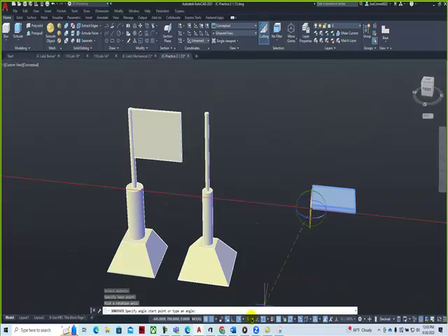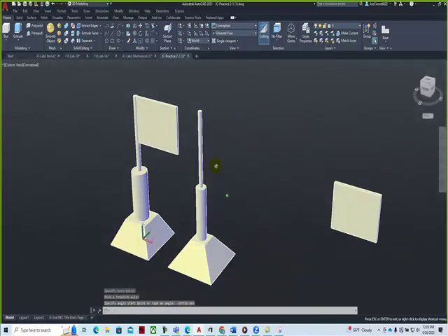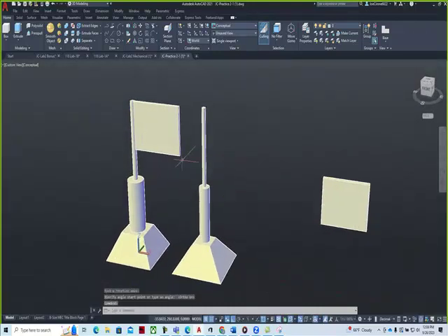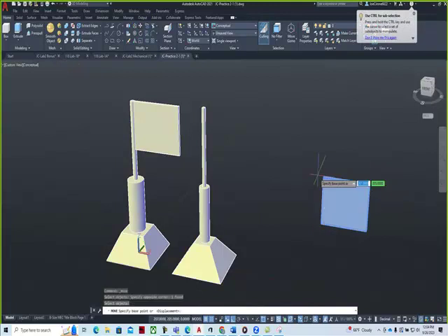Sometimes if I don't get it to track the right way, I'll turn on my ortho. That's F5, right? F8, please. F8, thanks. And that way it'll snap in 90-degree increments. And so ortho is definitely helpful because you want those things to move in 90-degree increments so they're not crooked. And then we just move it as you get better with 3D.